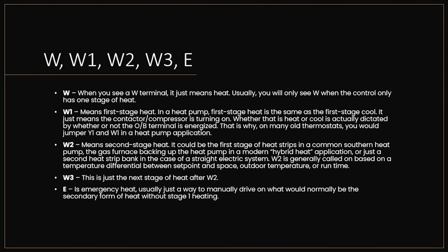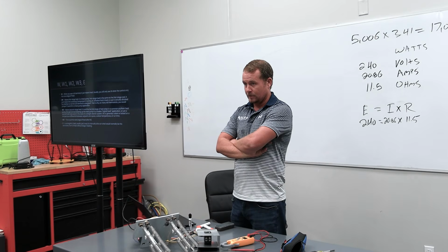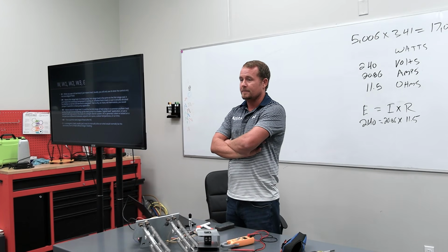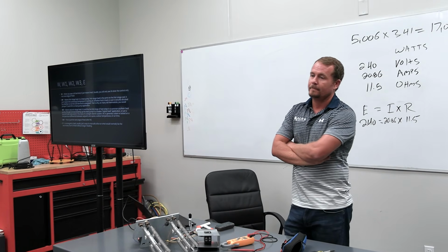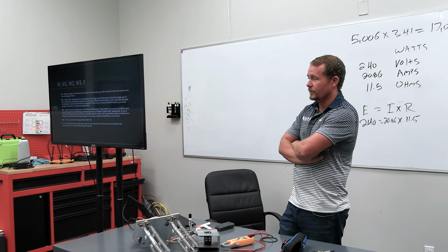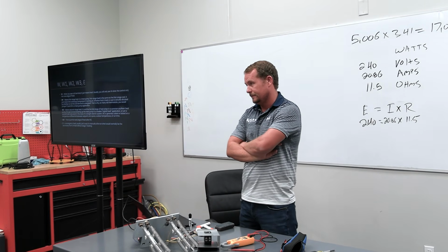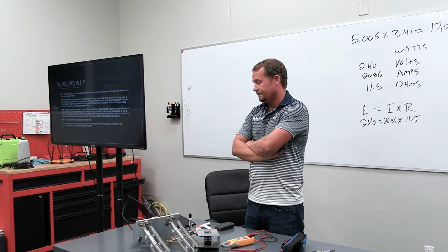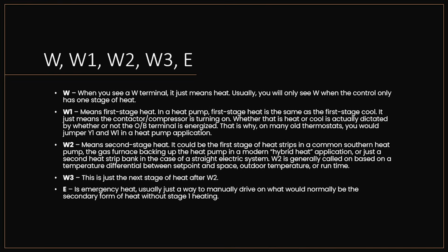W1 means first stage of heat, which could mean in a heat pump is what? What is first stage of heat in a heat pump? Carlos? First stage, the reversing valve? It's the compressor. Yeah, the compressor with the reversing valve de-energized typically. That's first stage of heat. W2 is electric heat in a typical single stage heat pump.